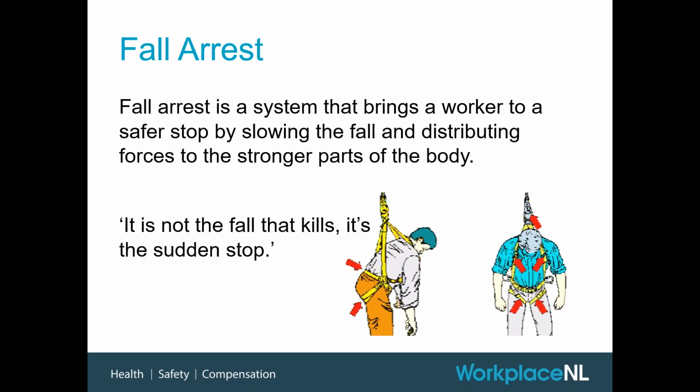Certainly body belts should never be used in a fall arrest system. They're prohibited. You could potentially use them in a fall restraint scenario, again, because the individual should never fall. However, I'm of the opinion that you're better off having the full body harness. Why go out and get a body belt when you can just use the harness, because you'll probably need it for something else in the future.